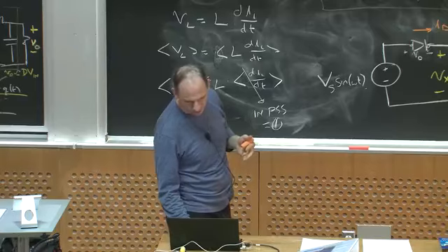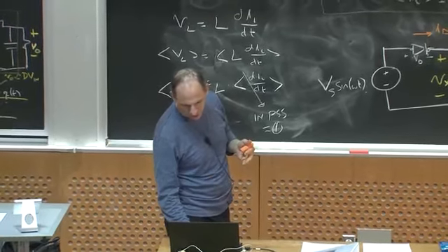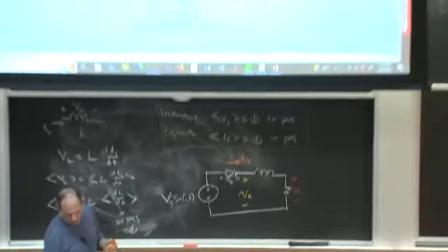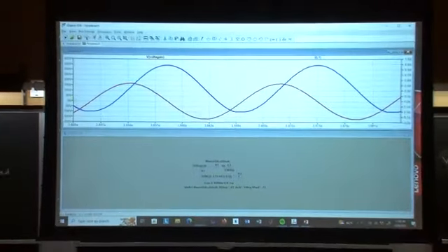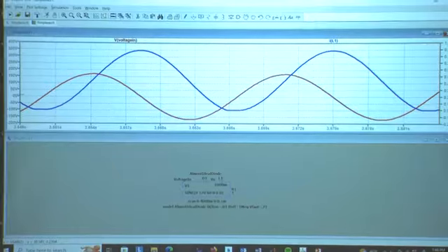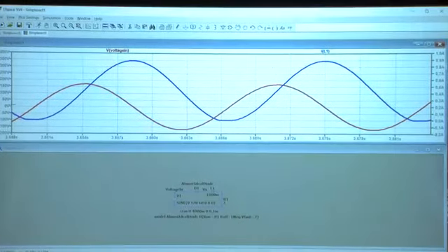And here you can see in red, on the left axis, we have voltage. It's just a sinusoidal voltage, and the 0 is here. Okay? In the right-hand axis, you can see the diode current. And what you can see is right when, just after the voltage crosses 0 positive, the diode current starts to ramp up. It goes up and up and up. It hits about just under an amp. But then the voltage gets negative, and boom, turns off.